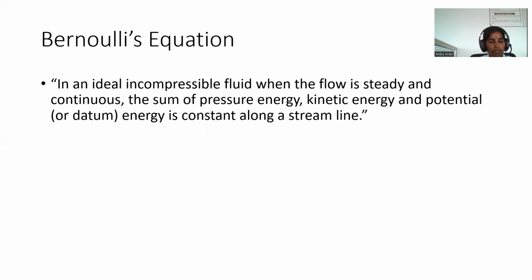Assumptions of Bernoulli's equation: the fluid is ideal, that is, the viscosity of the fluid is zero. The flow is steady and incompressible, and irrotational. Bernoulli's equation states that in a steady flow of an ideal incompressible fluid, the total energy at any point of the fluid is constant. The total energy consists of the pressure energy, kinetic energy, and potential energy or datum energy.